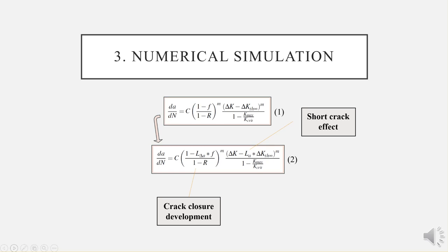To solve this issue, we considered that in Newman's work, the crack analyzed has been obtained by a crack growth process. In this situation, crack closure mechanisms have fully developed. In our case, the crack in its initial state has been directly manufactured in that configuration, so we can assume that no crack closure is present at the beginning of the fatigue test, but instead this needs to be progressively built up as the test goes on.